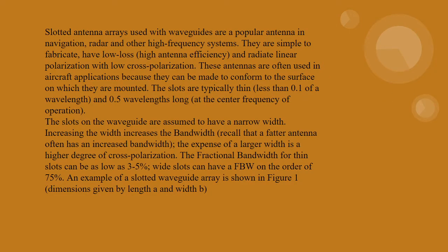So, slotted antenna arrays used with waveguides are popular antennas when it comes to navigation, radar, and other high frequency systems. They are simple to fabricate. They have low cost, especially high antenna efficiency. They radiate linear polarization with low cross polarization.